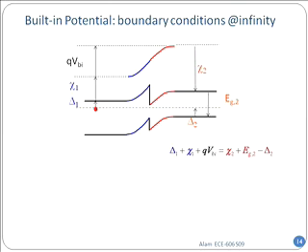Of course, because as soon as you know the doping, you know how far away the EF is with respect to EC, so therefore you know that. You know chi 1 and chi 2, right? Your reference book told you so. So you know that. The only thing you don't know, well, Eg2 you also know. The only thing you don't know is QVBI. So you're calculating QVBI.